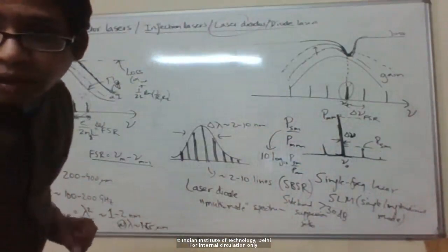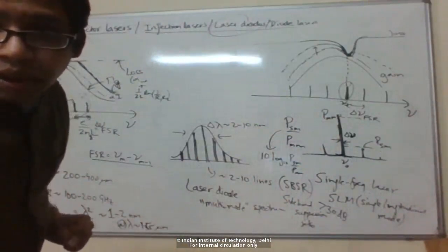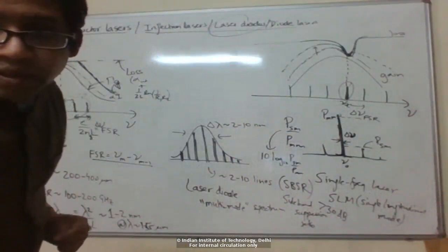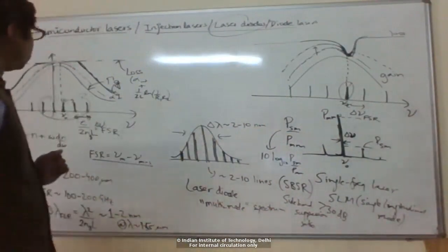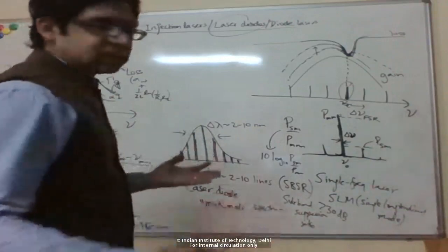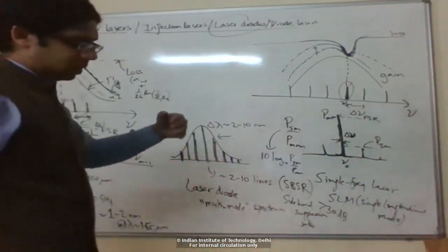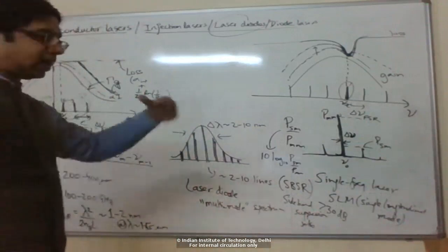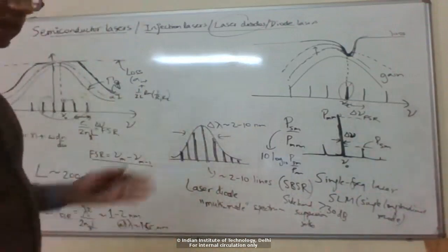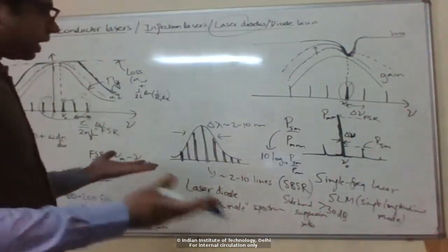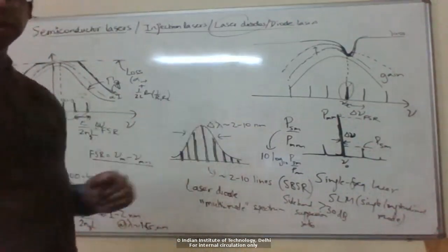There's another question of how to observe the modulation bandwidth of a semiconductor laser diode. That we'll study maybe in the next class, the modulation characteristics. Just like we discussed for an LED, if I modulate the current, my optical power output also will be modulated, and I can use that to encode electronic data onto the optical wave.